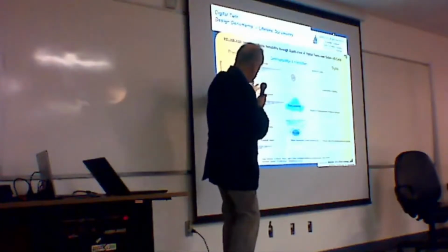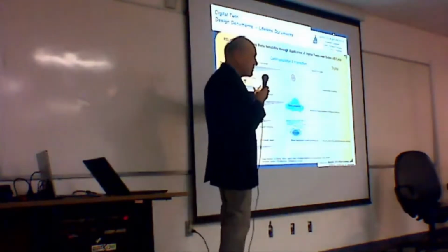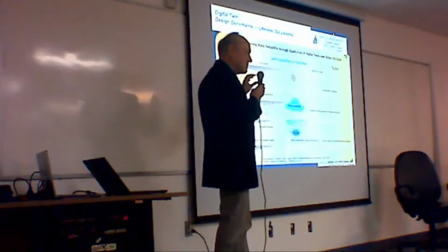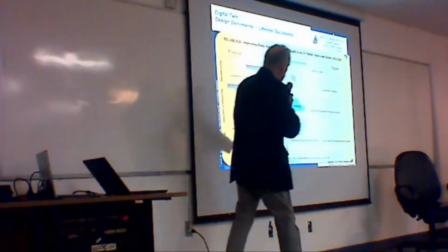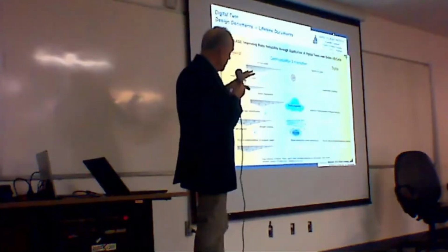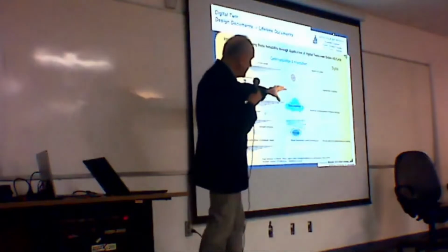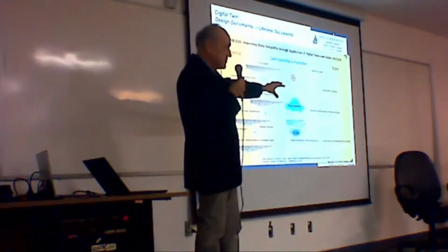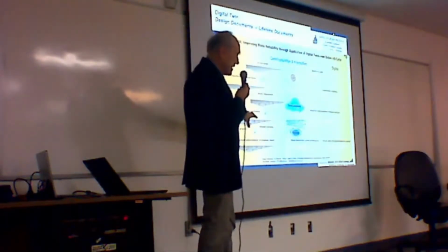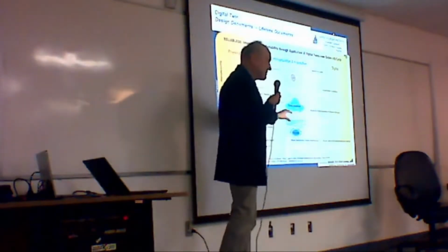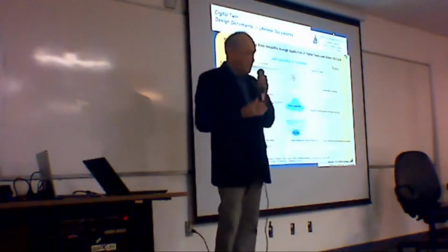You deploy sensors along the blades, and with the information, and that's important, the continuous exchange of information between the physical reality and the model allows us to have a numerical modeling of the defects, knowing the information from the sensors. We can then experiment with repairs for these defects and play them back to the real blade. And with the sensors, we even get the feedback whether this repair was successful or not. So just to give you an idea what digital twins are good for.